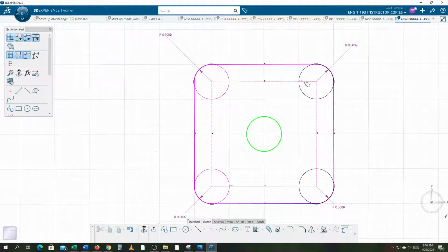So you don't want it to, it almost like it has to come in here and stop and do a 90-degree turn, stop and do a 90-degree turn. Since these are 90 degrees, that is no longer a tangent toolpath. The toolpath has discontinuity and tangency as it goes around, and that's what causes problems with the machine part.